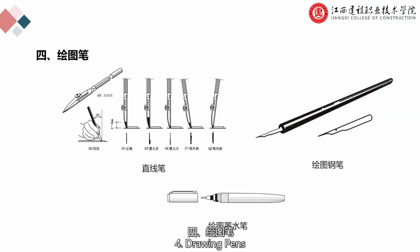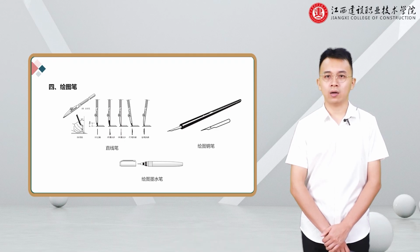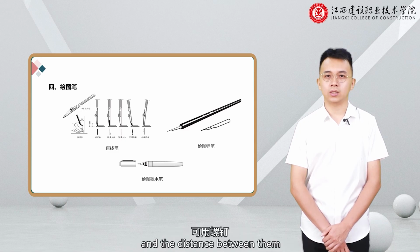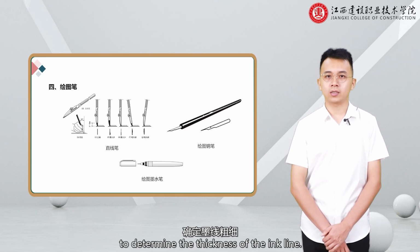Fourth, drawing pens. Common drawing pens include ruling pens, drawing fountain pens, technical pens, etc. The nib of the ruling pen is shaped like a duck's bill and is also known as a duck bill pen. It is a tool for drawing ink lines. The nib is composed of two steel blades, and the distance between them can be adjusted arbitrarily with a screw to determine the thickness of the ink line.